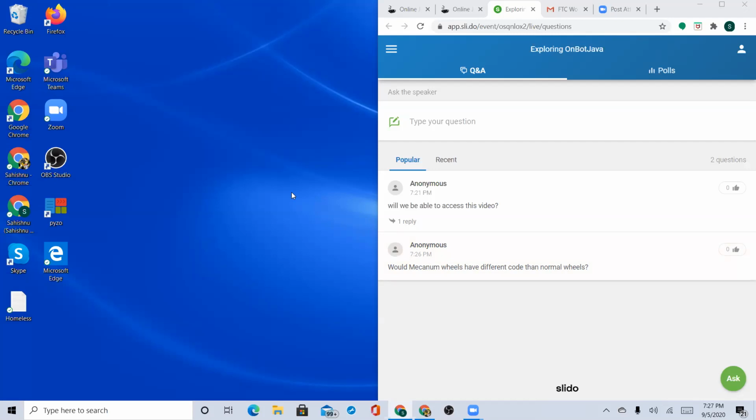So the horizontal movement and then omnidirectional, so you can truly move it completely, makes it so that you have to utilize the diagonals of the wheels correctly. So the diagonals are opposing each other. So if you want to code Mecanum wheels properly, you have to keep that knowledge in mind. I don't have quite the time to go into it fully, but Mecanum wheels are especially what I was referring to earlier, in that you are most certainly going to have several bugs when coding them, and they're exactly the kind of wheels that you want to test again and again and again, because it requires knowledge of which diagonals, moving which diagonal will move which other diagonal, which will move the wheels as a whole.